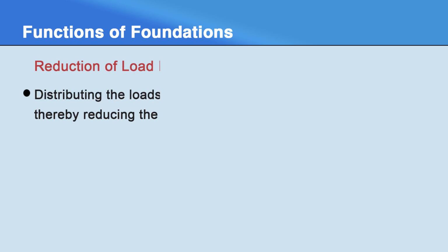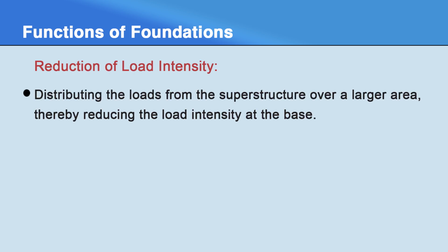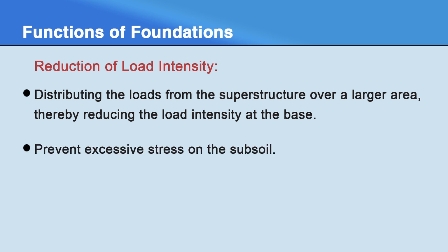Now, the next is functions of the foundations. Foundations serve the following purposes. First is reduction of the load intensity. Foundations play a crucial role in distributing the loads from the superstructure over a larger area, thereby reducing the load intensity at the base. This is essential to prevent excessive stress on the subsoil.